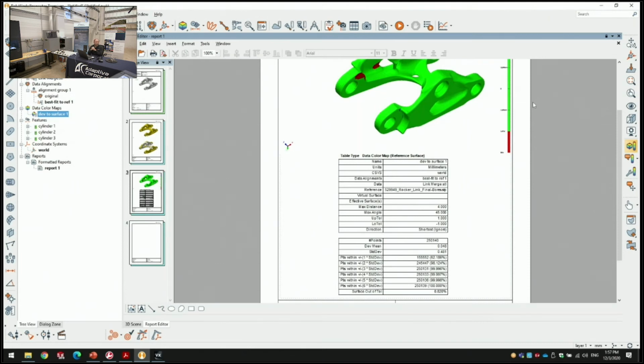If you're an aerospace company, you complete something called an AS9102. If you're in automotive or mobility, or really most industrial manufacturing companies, you would generate something called a PPAP. So from PolyWorks, I can populate the as measured data into the AS9102 or into the PPAP so that I'm not manually rekeying that.